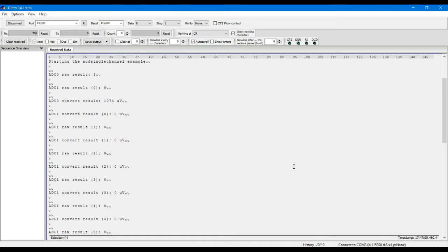So the thread was executed. After that, the ADC1 thread was taken up. The processor switched the thread to ADC1, or rather the thread function 1 was taken up. Over there I will have to make 10 samples. While it was being measured, while the raw result was being collected, the ADC1 raw result procedure was started.